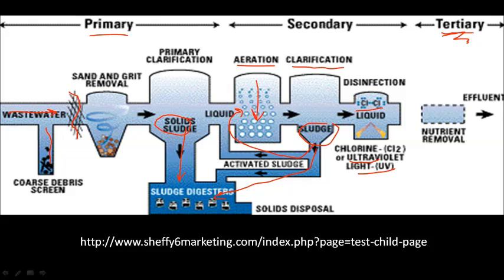But the methods of tertiary treatment will vary pretty extensively, and this is where some of the higher tech methods come in. So it's maybe not very surprising then that some of these tertiary wastewater treatment methods are the exact same types of methods that are used in the drinking water industry. And many water treatment plants that use some of these sophisticated methods produce an effluent that is actually, in terms of the level of microbes and other contaminants, fairly similar to the quality that we would expect from drinking water. And in fact, a lot of times the drinking water treatment process has less to do with removing dangerous microbes than it does with improving the aesthetic qualities of the water, the smell and the taste.